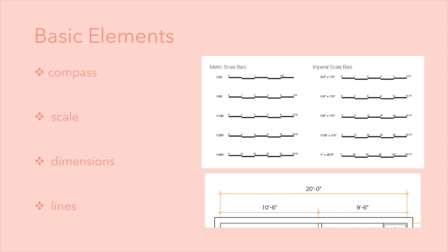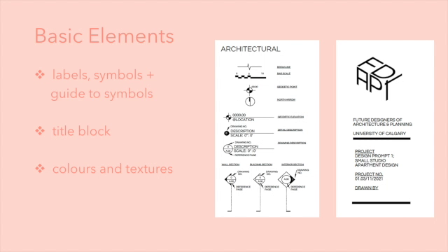As well, the kinds of lines that you use can convey certain information, so a solid line indicates a visible solid object, or it can also be used for dimension lines and flow lines as well. Hidden objects or edges of things can be drawn with short dashed lines. The way that you use these lines is, again, more up to you, but these are just the basic typical uses of lines in a plan.